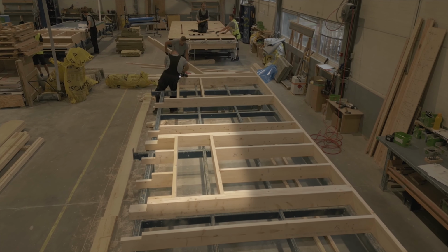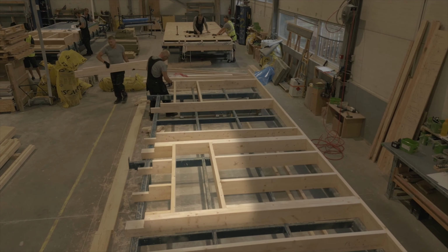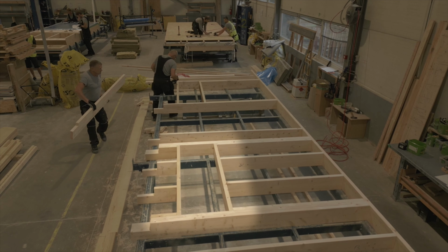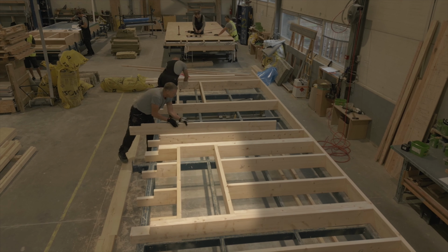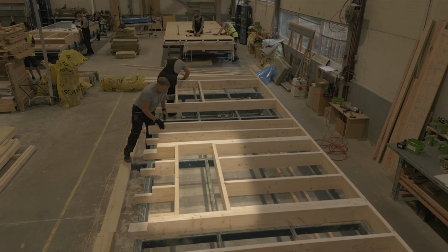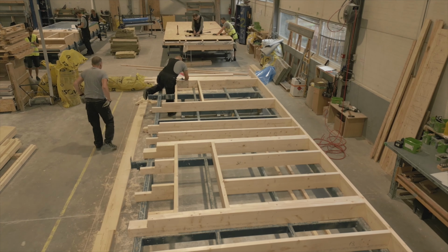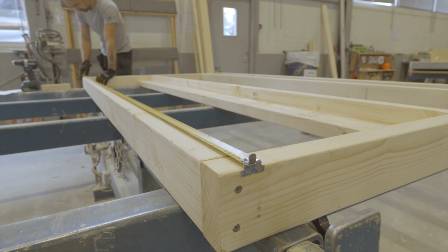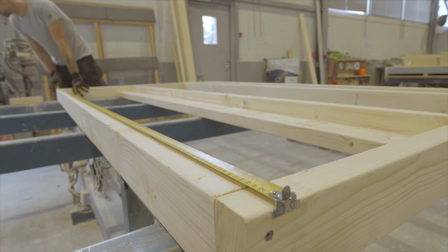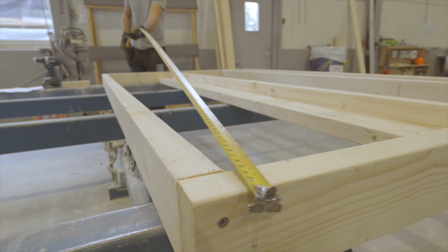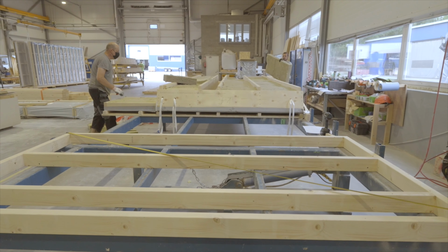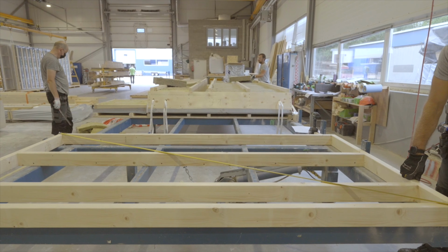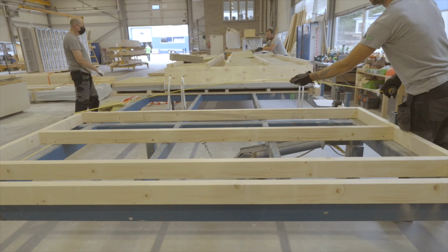If openings are provided in the wall, like a window, then between the frame studs you need to install intermediate beams that form the framework of the opening filler. After completing the assembly of the wall element frame, it is necessary to recheck the elements, the overall dimensions, diagonals, and positions of the structure must also be checked.